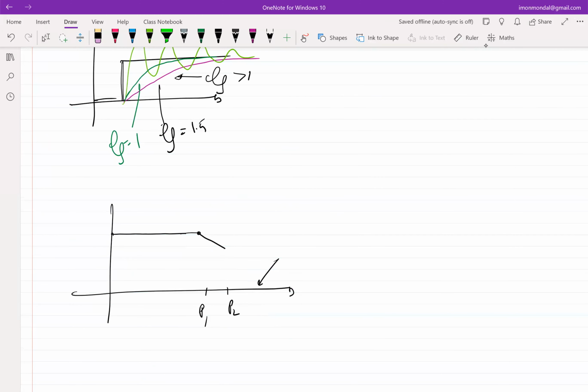An extreme case is if omega UGB is much higher than P1 and P2, then tan inverse of each of those terms becomes -90, -90, it goes to -180, right? It's unstable, or rather marginally stable. So even if you don't go there, the phase margin will tank simply because you have two negative terms to deal with, right?